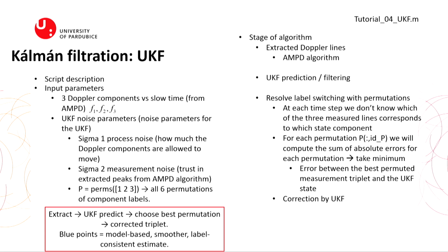And after you find it, you need to recompute, compute this amplitude, make averaging, and then you will find these Doppler frequencies. Then you need to compute all combinations, because you don't know whether the first one was the first sine wave or the second or third.